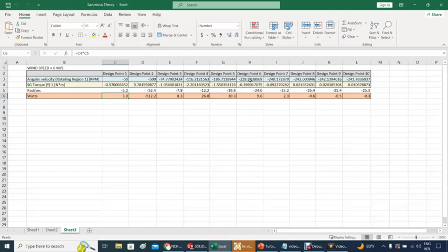Now if you get to 229, the torque is so low that you start to drop back again in terms of watts. At 229 you produce only 9.6, because although the RPM is high, the torque is almost not there anymore, so that's not good. So you want to look somewhere close to, perhaps on the white, 186 might be a good one. Look into that RPM, it might provide you a good energy extraction.